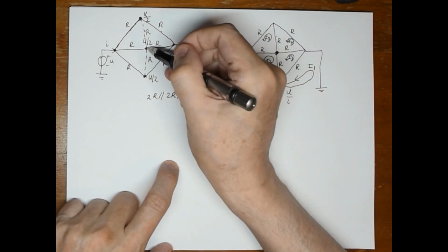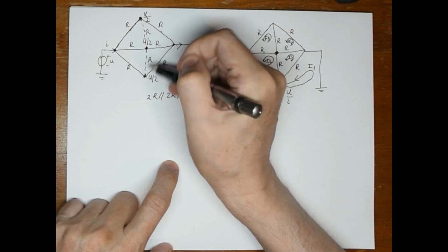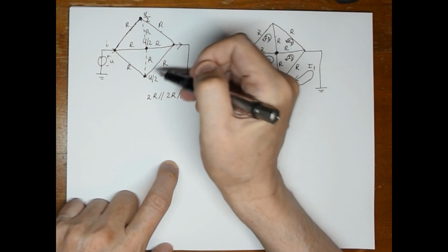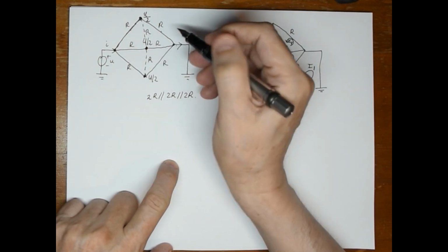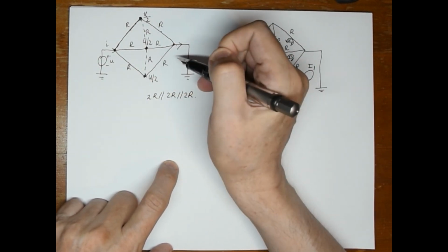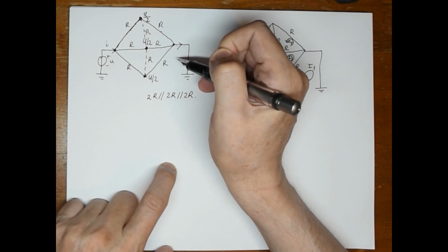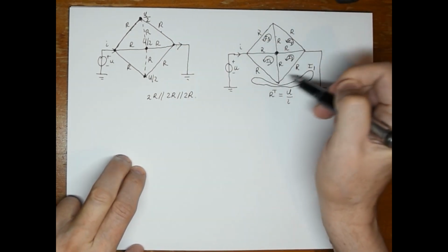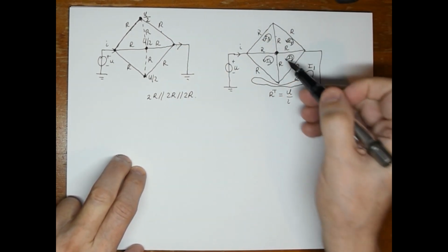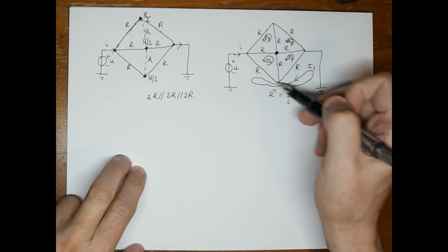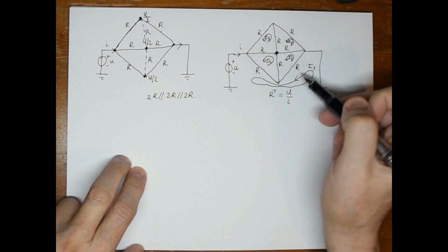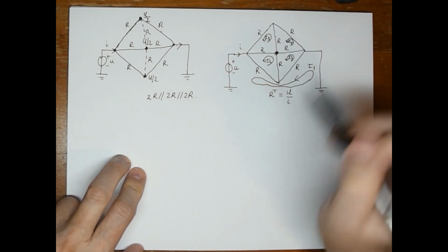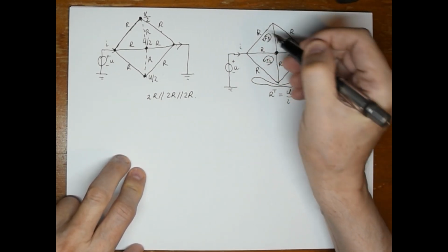Because there's a voltage difference of 0 between this node and this node, there cannot be a current running through here. So you might as well insert them. It's not going to make a difference for the total resistance or for the circuit's behavior. The behavior will be exactly the same. So this very complicated circuit that you usually solve by defining 5 equations, solving them with 5 unknowns, getting the various currents, and as a consequence getting the replacement resistance RT.